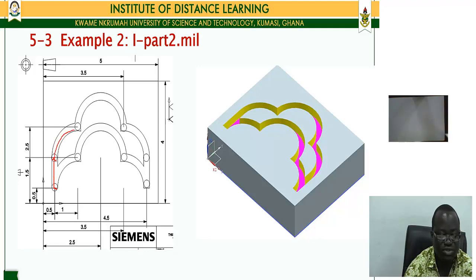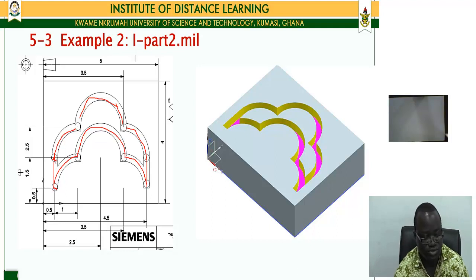So we have the tool start position here. It moves up this way. It creates this arc in this fashion. It continues and creates this arc further this way, in this direction, and then creates this next arc, and then does a linear feed down like that, and starts another arc creation from here in the counterclockwise direction, and creates this arc here, and then finally generates this arc.